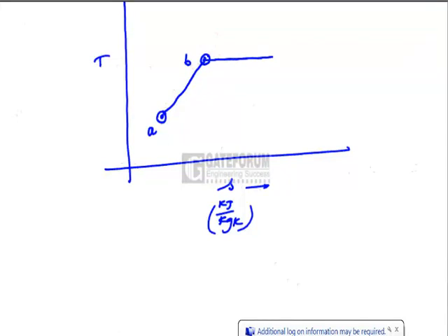When heat is supplied to the saturated liquid, temperature remains constant, but entropy keeps on increasing because heat is supplied. The change of phase completes at state D, where the state D can be taken as a dry saturated vapor state. Between state B and state D, let me take state C, which corresponds to the wet mixture state, which is a mixture of liquid water and vapor, in thermodynamic equilibrium at saturation pressure and saturation temperature. State D is the dry saturated vapor, which has just completed its change of phase.